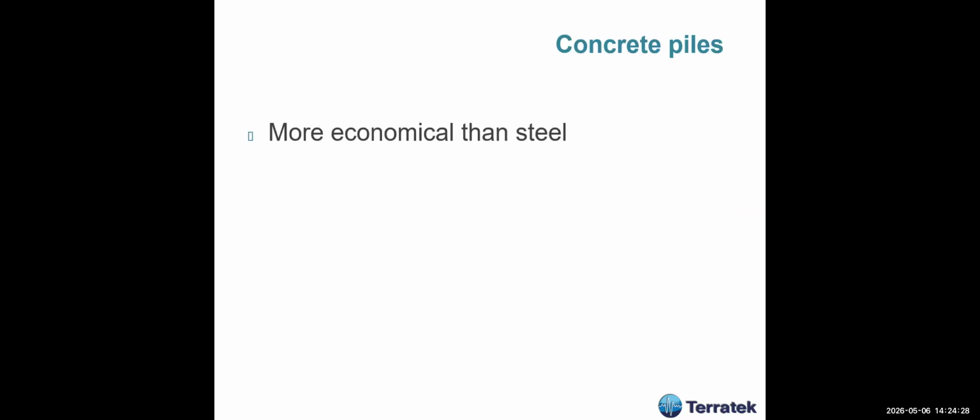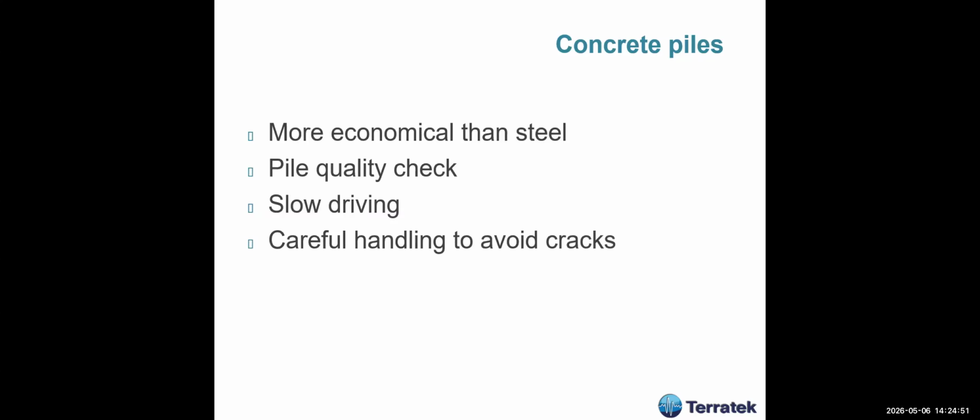And concrete piles, as a summary, they are more economical than steel piles. We have to do pile quality check, absolutely necessary. You have to drive them slowly. Why? Otherwise, you may damage the pile. So you have to do much more careful driving of these piles, careful handling to avoid cracks.